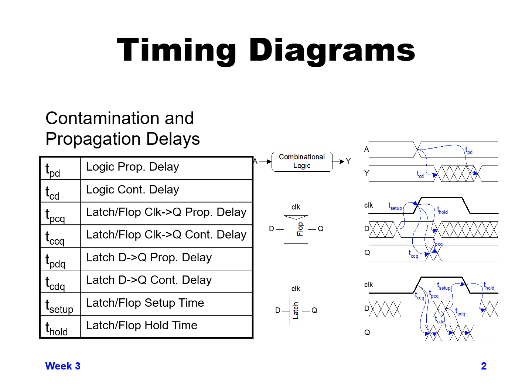So next, let's look at the second row where we have clock going to a flop. In this case, we have basically 4 different timings that we care about. Since we only sample the value of D when clock is rising, for the most part we're just concerned with what happens relative to the clock rising edge.